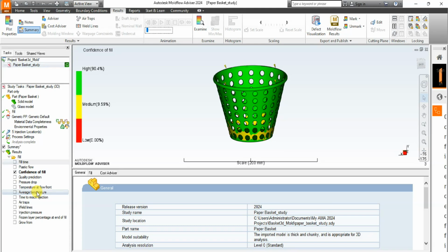Now, if you're working under the advisor, the advisor uses these two items for information to calculate the risks of producing this part with the following sliding scale. When you see all green, like I said, the part is easily filled and quality should be acceptable. The part may be difficult if it is yellow. The part may be difficult to mold or quality may not be acceptable as the percentage of yellow increases. So the yellowness must be minimal, in its barest form. This is very, very important.